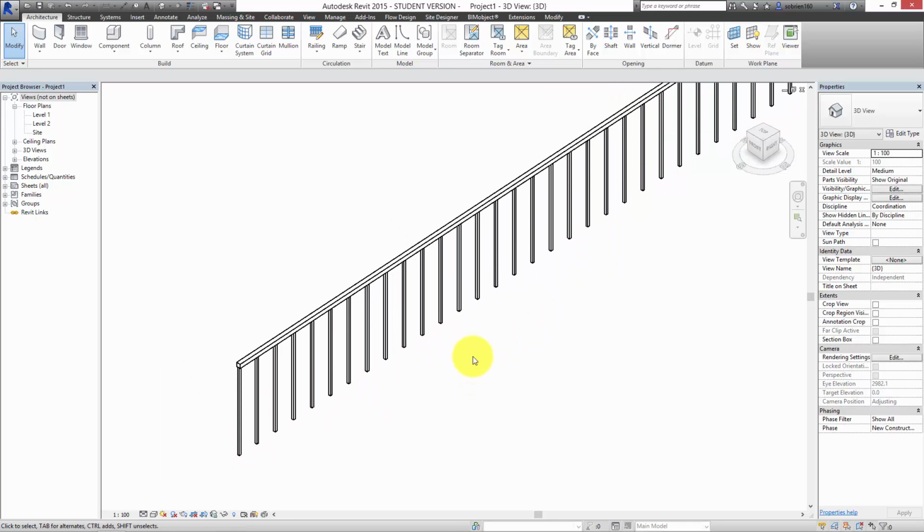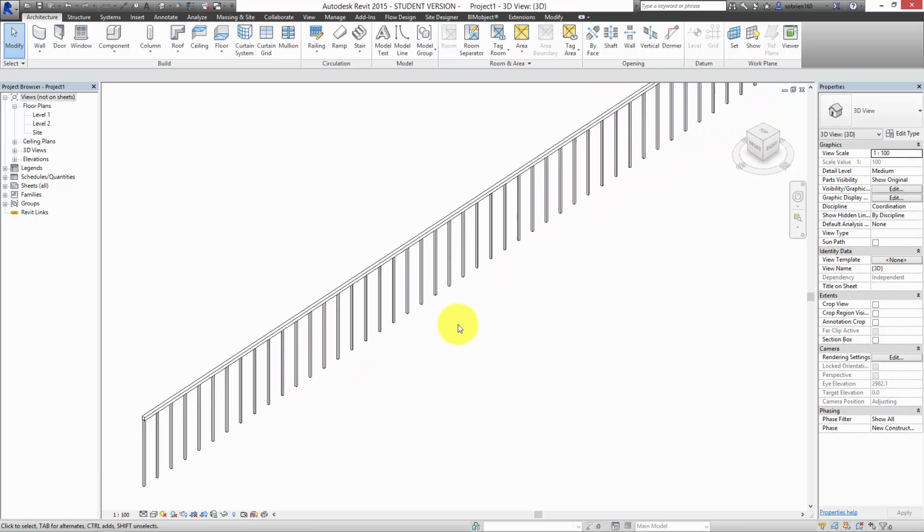Railings can be used to make anything that has that combination of vertical and horizontal elements. So often people use it to make sunshades or whatever out of aluminium, because it's the quickest way to do it. All you do is make a baluster that repeats, and then make a rail that acts as the sunshade, and you just multiply it. So you can very quickly make a sunshade that way. I've got a video about that in the 4th semester stuff.